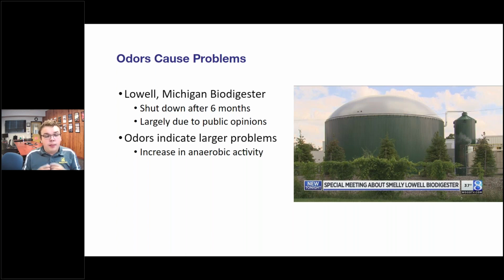So with a lagoon, you may be thinking the lagoon's working fine, I'm making my permit, but it smells horrible. If it's smelling horrible, you don't want to just sit there and let it go because it could result in bigger problems. Odors in a lagoon system typically mean you have an increase in anaerobic activity, which means the lagoon is actually reacting slower than you would normally expect it to.